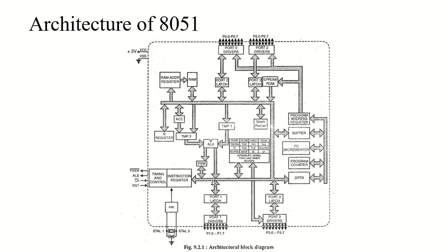Now the 8051 also has three general purpose user flags, right? These flags can be changed from 1 to 0 by the programmer based on his or her desire. The flags used for general purposes are called F0, GF0 and GF1. The PSW contains the user flag F0, while the GF0 and GF1 flags are stored in the PCON register. No need to worry, we are coming to the PCON register as well.